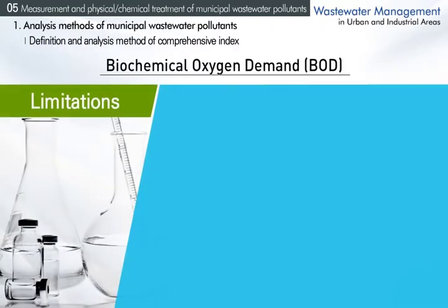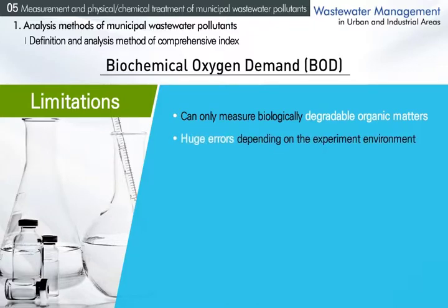However, since BOD measures pollutants based on microorganisms' metabolism, it has various limitations. First, it can only measure biologically degradable organic matters. And second, it has a huge error depending on the experiment environment, such as temperature, skill of experimenter, and the types of microorganisms seeded.